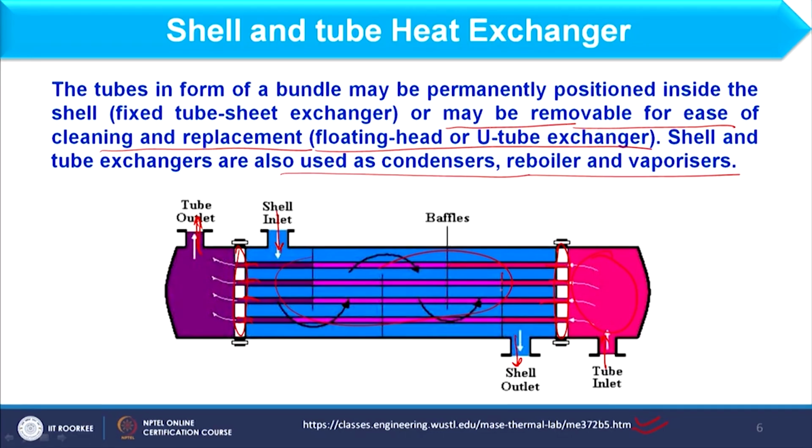Okay. Now, next we have these baffles. Okay. Some part of the baffle is removed so that liquid can move. So, this baffle basically provides the movement of the liquid in the shell side, along with it holds the tube, because in the pattern the tube sheet has holes. In the same pattern the baffle has holes, so that tubes can be inserted in the baffle.